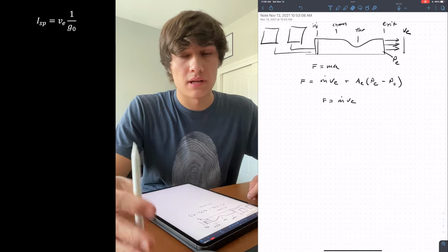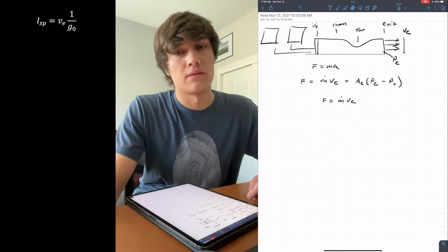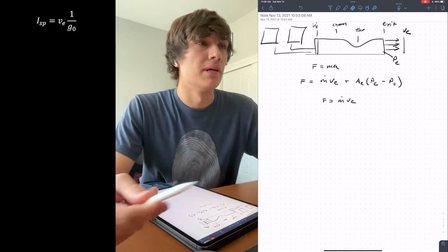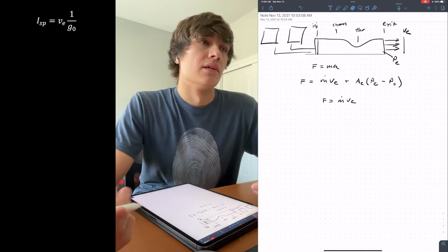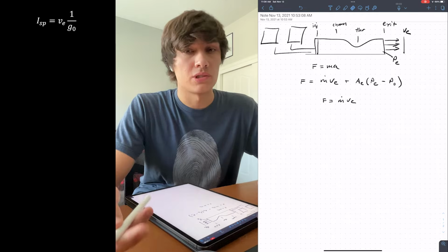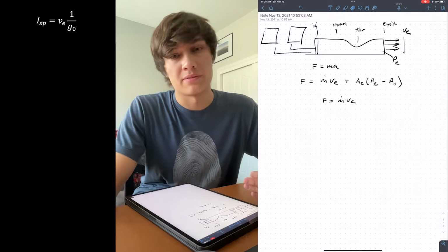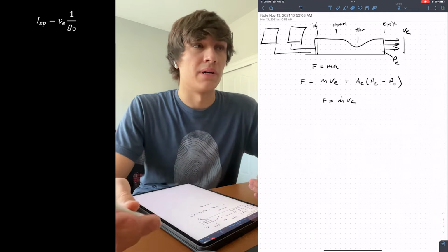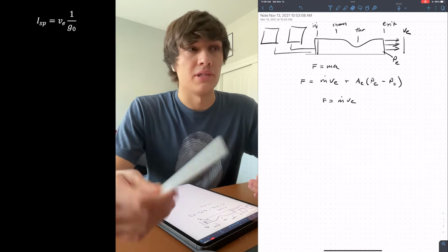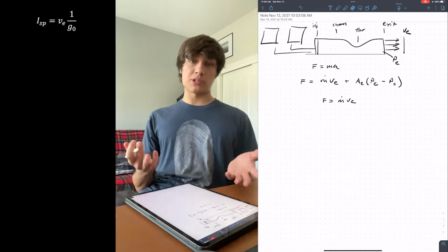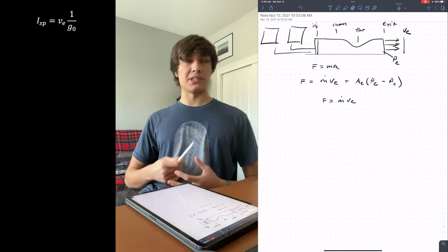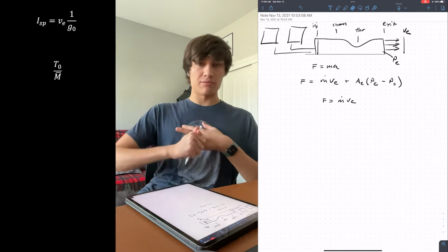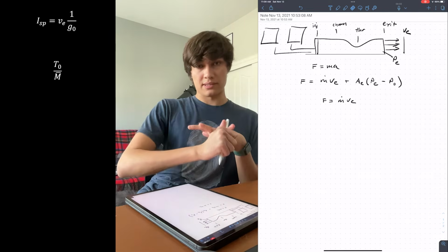Let's talk about some quick examples of some fuel and liquid oxygen combinations and what kind of specific impulses you can expect out of them, given that you're optimizing the engine. So kerosene liquid oxygen usually goes in the 250 to 350 seconds range of specific impulse. Liquid methane is 300 to 380. And then liquid hydrogen is 400 to 460. Now the question becomes, why are they different? Or maybe a better question is, what governs rocket engine efficiency? And the answer is the temperature of the combustion and the average molecular mass of the exit products.